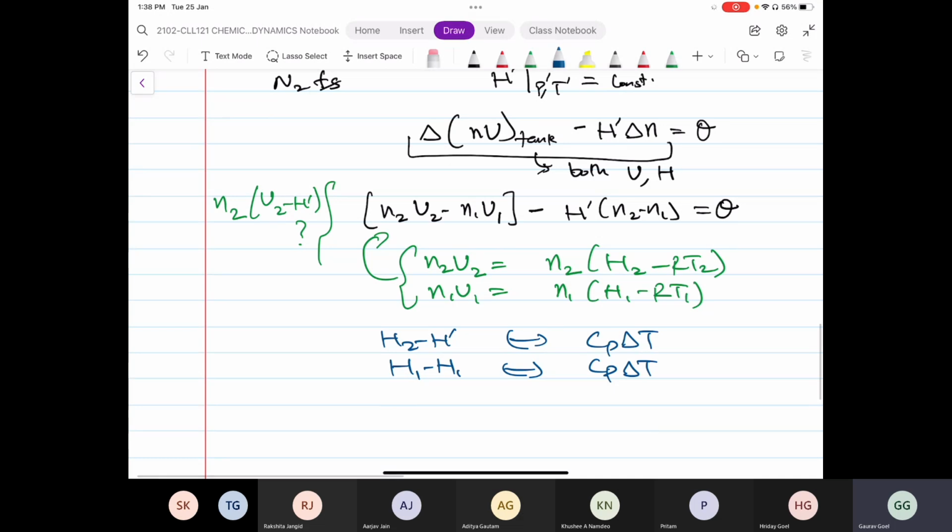Okay, now that is slightly hypothetical. The reason is nitrogen, typically the way you are filling nitrogen cylinders, nitrogen is not at ideal gas like condition. So here, whatever data you have been given in this problem statement, they are saying that pressure and temperature conditions are such that nitrogen can be modeled as an ideal gas. Okay, so of course it made the calculation easy, but it took the problem away from practicality. So we will kind of revisit this problem. So from a relevance perspective, we have not fully trained ourselves.